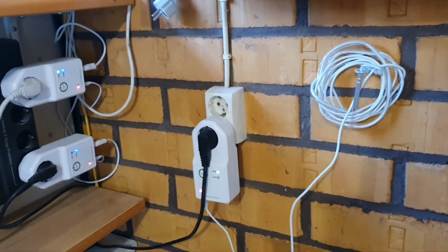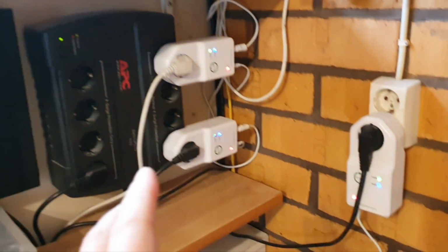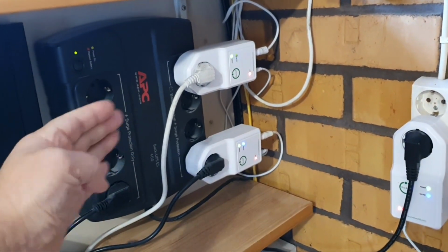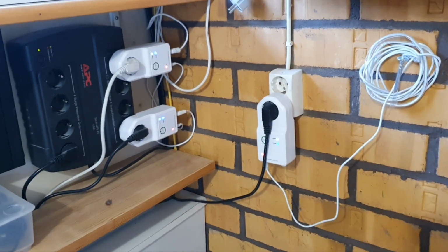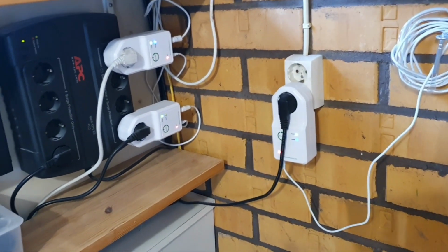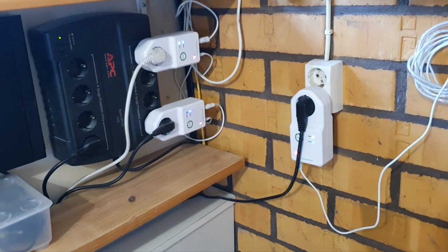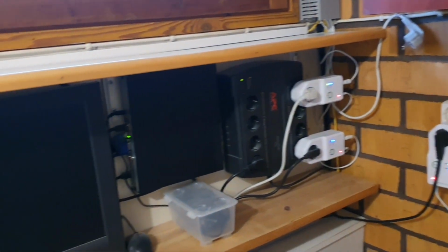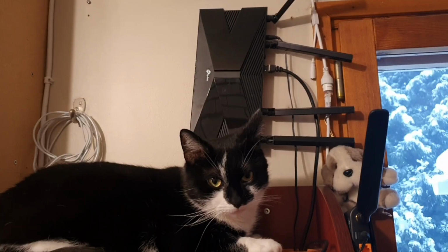They also monitor the temperature inside, temperature outdoor, power cuts before backup power, the UPS, and after the UPS, which means detection of flat battery. However, today I want to focus just on remote reboot, switch on off feature, and power consumption monitoring features. And because they are cellular or mobile, I can use them on the location where Wi-Fi is not available, or Wi-Fi is exactly the subject to be rebooted.